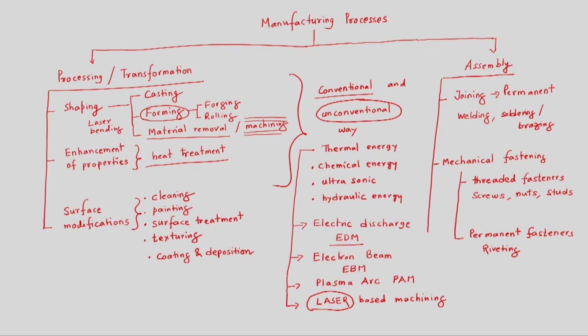Lasers are also used for the surface modification, that is laser shock peening and laser texturing as well. Lasers are also used for coating operation. So, laser based cladding we can do, or laser based deposition is also possible. So, lasers are not only used in transformation operation, they are also used in joining operation, that is laser welding.